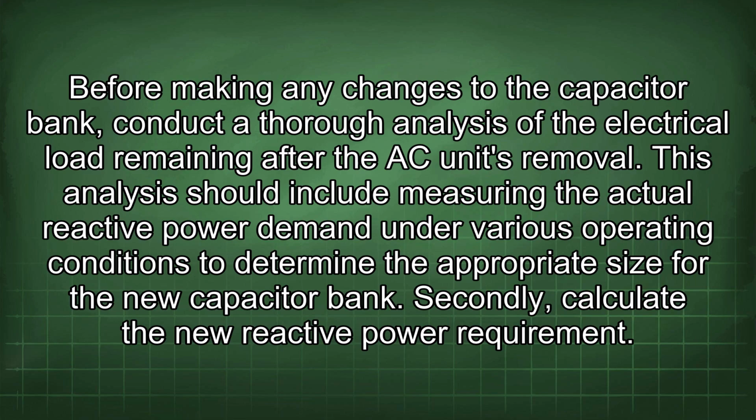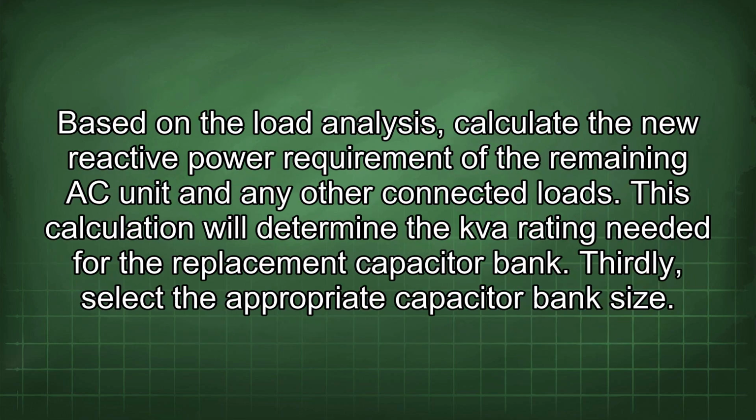Secondly, calculate the new reactive power requirement. Based on the load analysis, calculate the new reactive power requirement of the remaining AC unit and any other connected loads. This calculation will determine the kVA rating needed for the replacement capacitor bank.